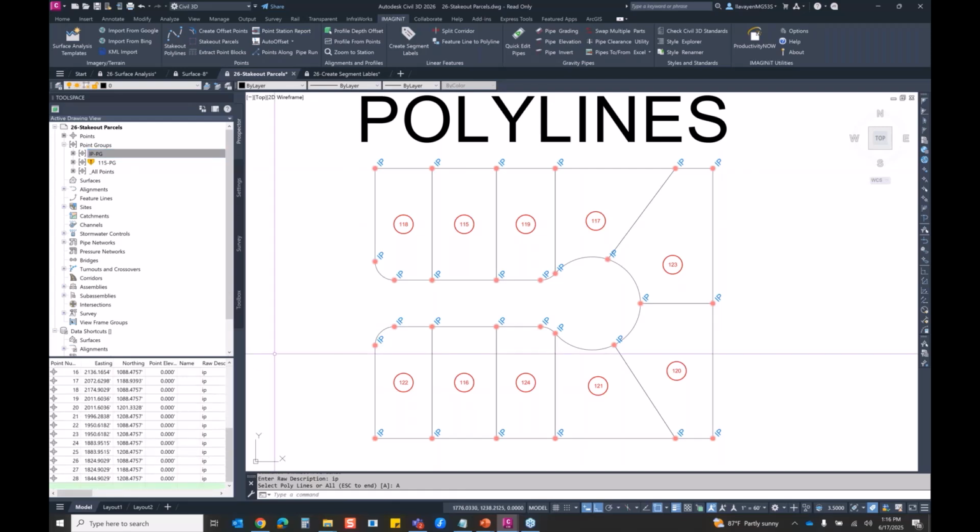I did a lowercase IP, just in this case, it's showing those all over the place here. The fun part about this, there is a left parcel and there's a right parcel inside of here denoted by polylines. Note that there's 2 lines available inside of there. Yet as far as creation, if I take that point and move it out of the way, there's only 1 point that was created there. So the tool was intelligent enough to note that there was a shared vertex there and it didn't double down on points for you. So this is the first iteration of this tool set, and I like it a lot.